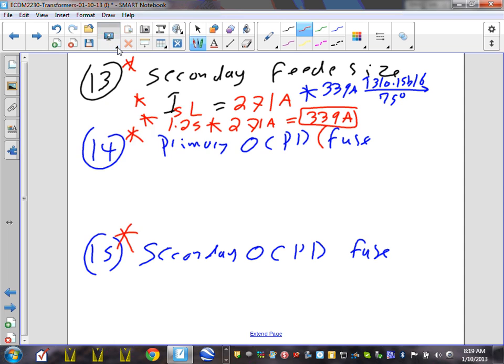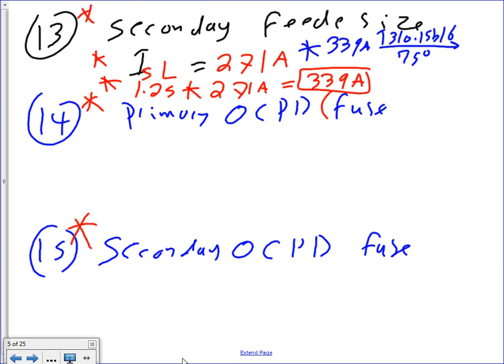So let's go size it. I'm going to go right in here. Here are the rules. Up to 300 amps, probably 300 to 400, full neutral, because of your receptacle panels. Higher than that, we start derating the neutral. I'll show you later on a bigger example. So for this time, I decided to use a full neutral. That's a decision you have made. So I'm going to go over here and take how many conductors?